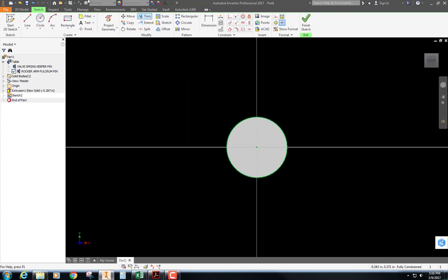When I go back and forth, it messes up. Thank you. So 0.187. So flange diameter equal 0.187. And it does not like it. Do you see how it stays red? So you have to have an underscore in between that for your parameters only.